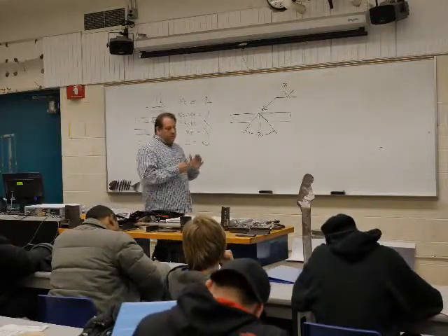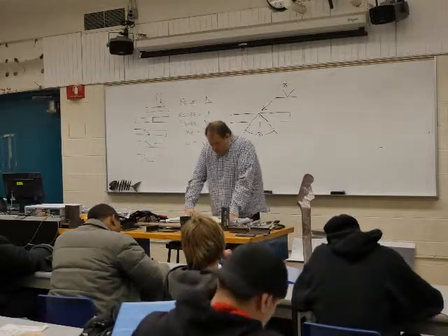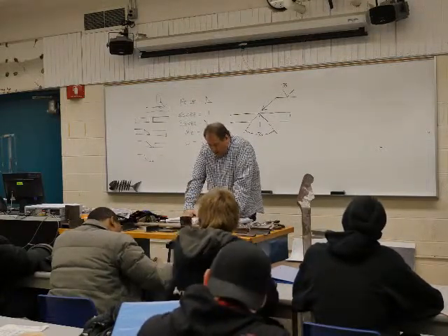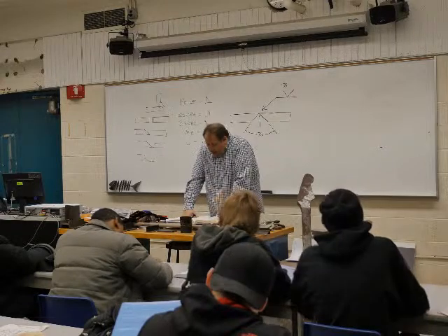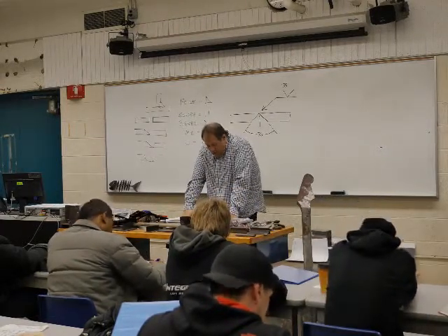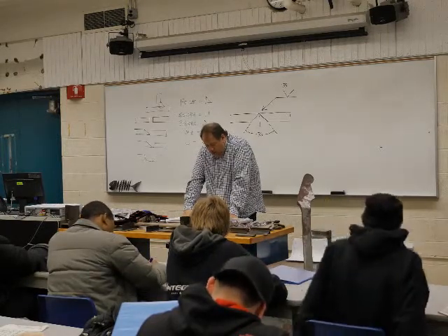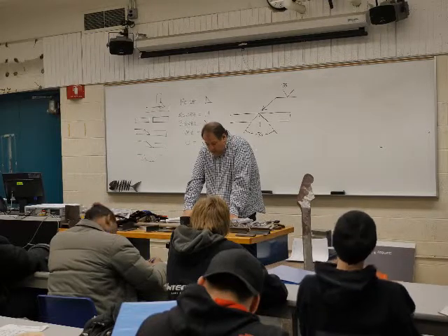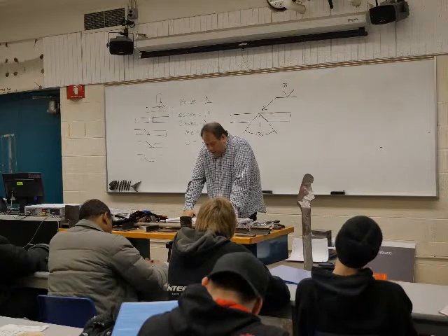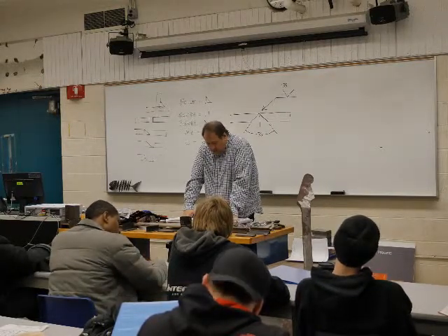Let's look at this symbol for a second. What we've done is we've done the arrow, we've done the weld all around, we've done the field weld, we've done length, but we haven't done that thing called pitch yet. But we'll get to that. We have a tail section. We have the actual welding symbol. We have a groove angle included, or countersink, but we're not dealing with plug weld, so it doesn't really matter.